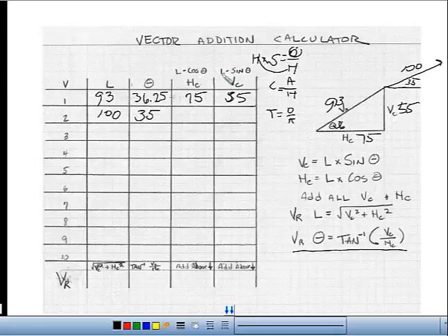Take the length of the hypotenuse, or the vector length, times the sine of the phase angle. Do it in that order. Get used to, drill it into your brain, get habituated to putting the vector first, then the sine of the angle. You'll find you'll have much less problem with the calculators we use in class, because if you do it in the opposite direction and forget to close your parentheses after plugging in the angle value, you'll end up with a very odd answer most of the time.